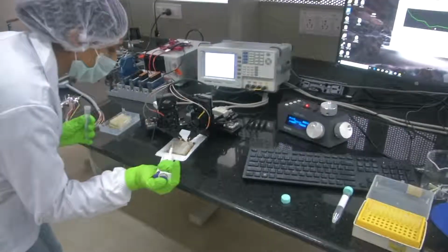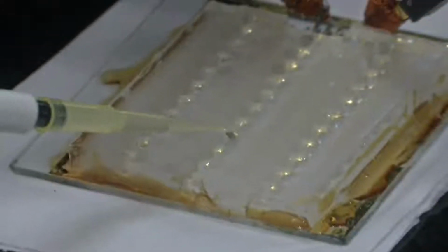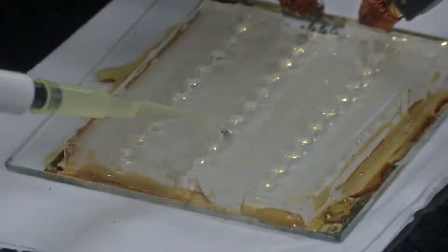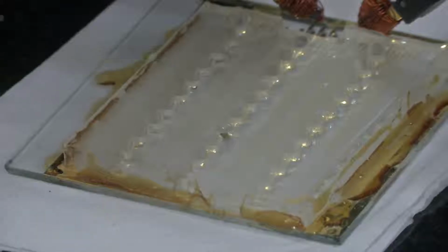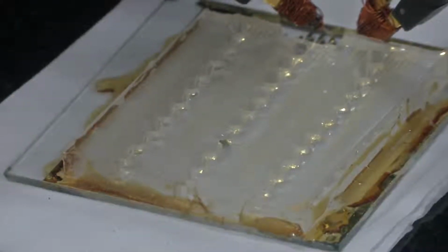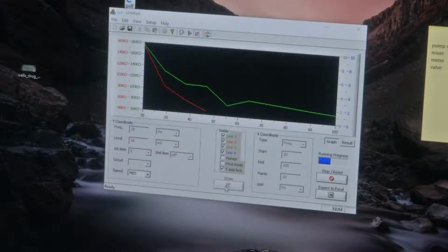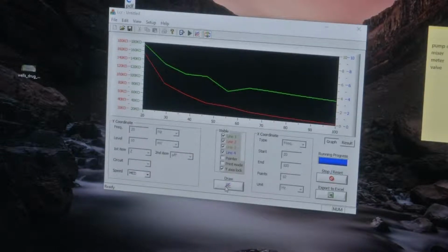Going to the third well. So here I fill the third well with salt water. Let's see what the impedance is. You could see there is a drastic drop in the impedance. Like we all know, salt water is a good electrolyte. You can see the difference in the resistance. So over the given frequency there is a drastic drop in the impedance.